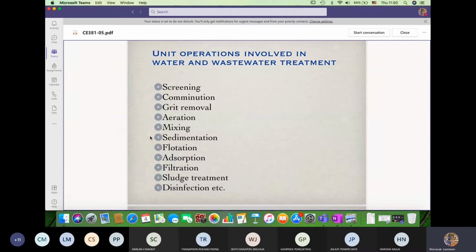Activated carbon does filtration, but it also does adsorption. The main removal process is adsorption. So activated carbon is able to adsorb the pollutants. Adsorption is more or less used in the advanced treatment process, or the tertiary treatment process. Normally, we do not apply this process at water treatment plants or large-capacity production because it's very costly, although we are sure that it can produce very good quality water. But anyway, it is very pricey.